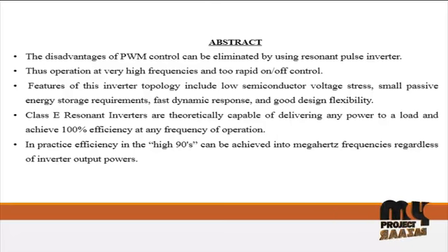Resonance switching topologies are the next generation of power conversion circuits when compared to traditional pulse width modulation topologies. Resonance-based supplies are more efficient than their PWM counterparts. This is due to the zero current and/or zero voltage transistor switching that is inherent in resonance supply designs. This feature also provides an additional benefit of eliminating undesirable electromagnetic radiation normally associated with switching supplies.